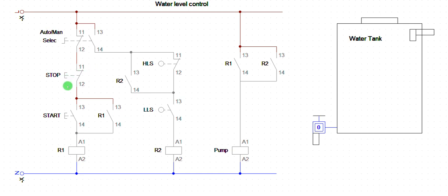That's a manual operation. Now, auto mode, you activate here. Here we open, then this one will close. Then you have power here ready. Now, the position of the switch, the water level sensor, will depend on which level is activated. Is it empty? If it is empty, in that case, you activate this. If it is filled up, this one is going to be activated. So let's assume it is empty. Let me activate this. Look at it. You see that this one comes up and is pumping. It will remain on and the water starts pumping, until water fills up and comes to meet this second switch. That is the high level switch. It will now shut down the system.